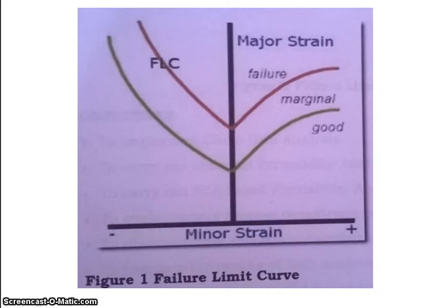It is necessary to assess the formability experimentally before manufacturing the actual component, to judge its stretching capability. The stretching primarily depends upon the limit strains. The limit strains are sensitive to the strain distribution, as shown by Keeler and Goodwin. The limit strains are described by the concept of the forming limit curve. The forming limit curve represents the onset of localized necking over all possible combinations of the strains in the plane of